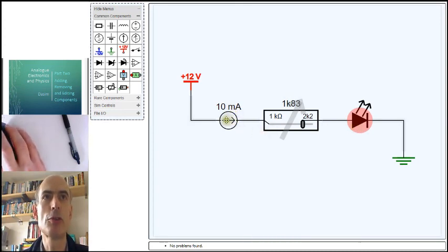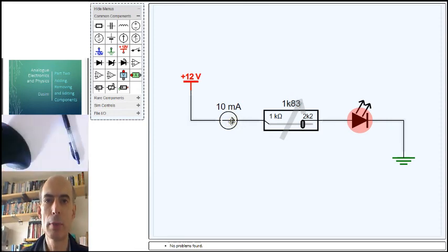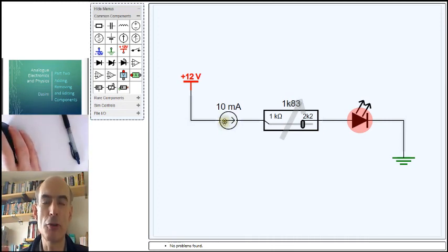It forces a current through this. You can't go and buy a component which is a current source. You have to make one out of other components. It's like sort of a macro. It's a simplified way of thinking about various types of circuitry which have this property of maintaining the same current going through them. But it's not like a battery or a resistor that you go and just pick one out of the shelves and use. But they're very useful circuits in analysing more complicated circuits, as we'll see later.